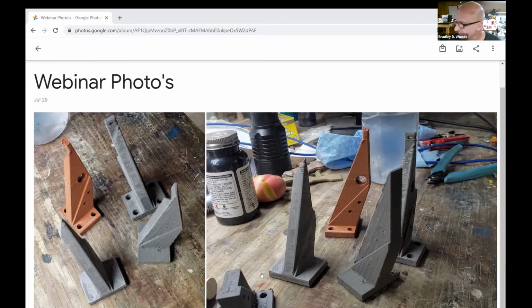I kind of wish I'd taken a better picture of this. I don't have a good picture, but I'll try holding it up to the screen. So this is 316L, and the flat shiny spot, I flattened it off on my mill. It mills great pre-sintering. It's not gummy. You get nice clean chips off the cutting tool.